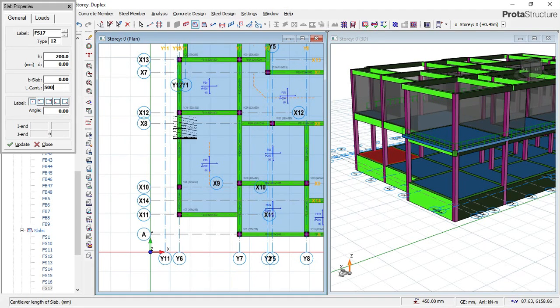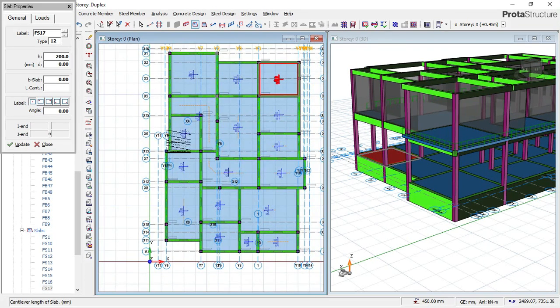So if during our design the beams are still failing at the edges, or the slabs around there are still failing, then we will go and increase the length of the toe for this ground beam. This toe is simply the same toe that you know when you're designing what they call a retaining wall.